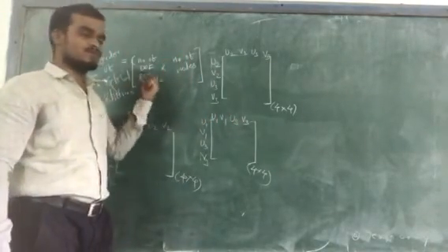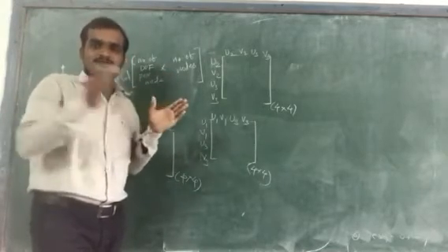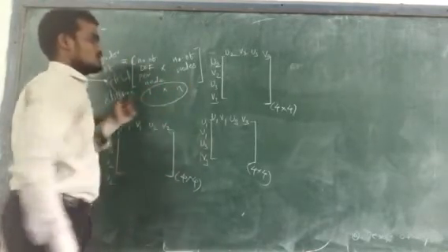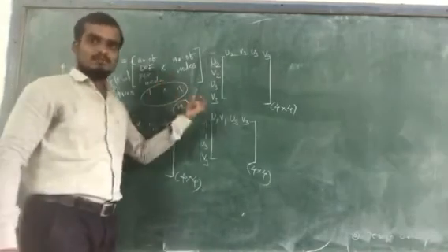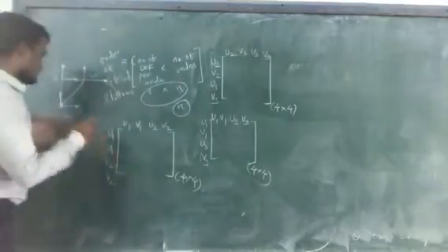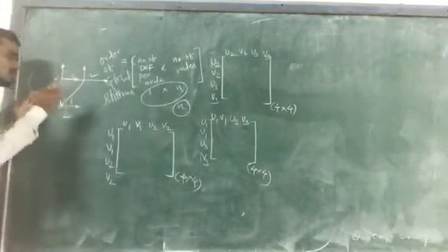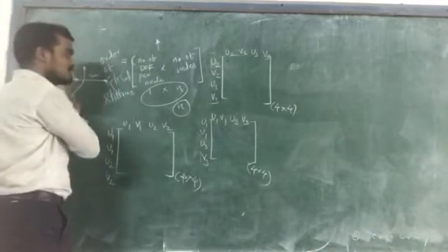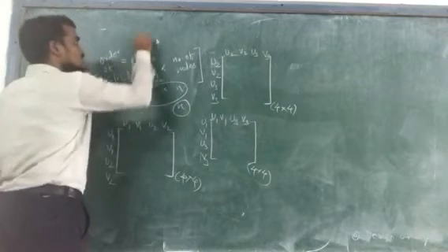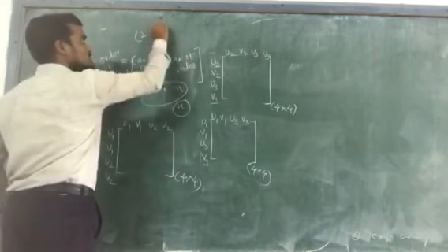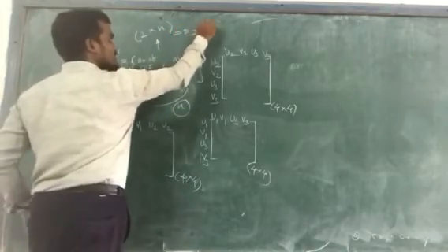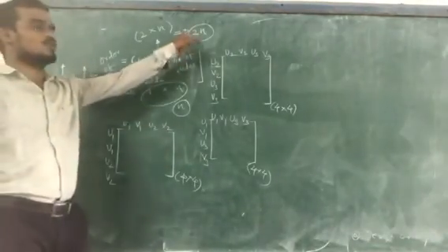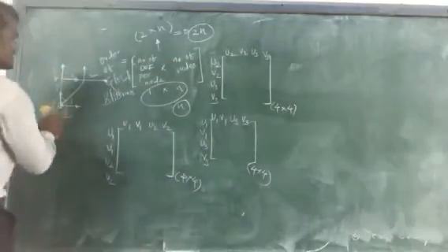So if we take the spring system, as we know that for the spring system at every node there is a horizontal movement in x direction, so there must be only 1 degree of freedom. So 1 degree of freedom into number of nodes n. So order will become n, where n is the number of nodes. But in the case of the truss element, we know that there is a horizontal movement as well as vertical movement. So there are 2 degrees of freedom at each node. So the order of the global stiffness matrix for the truss element will become 2 degrees of freedom per node into number of nodes n. So it will become 2 times n, means 2 times the number of nodes. Okay, so this is clear.